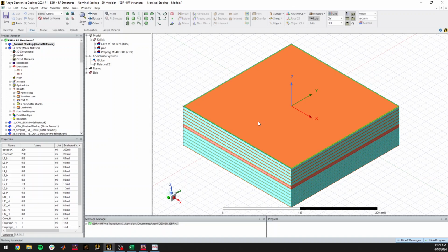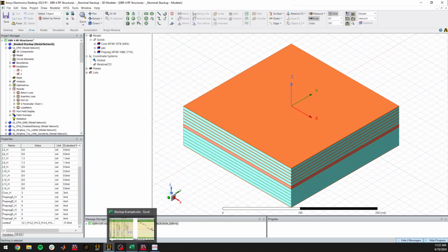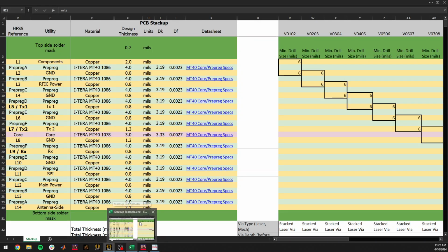And in this case, like I said, it was a 14-layer PCB. I prefer to parameterize everything here, whether it be the coupon size. Coupon is what I'm calling the puck here, or the sample of the PCB. And also have everything else, including the copper layers and the core thickness and the prepreg thickness, all be given a variable so that it can be adjustable moving forward. And you could even step back one step further, and whether you're doing this in Altium or whatever your PCB layout software is, in this case I just use Excel.